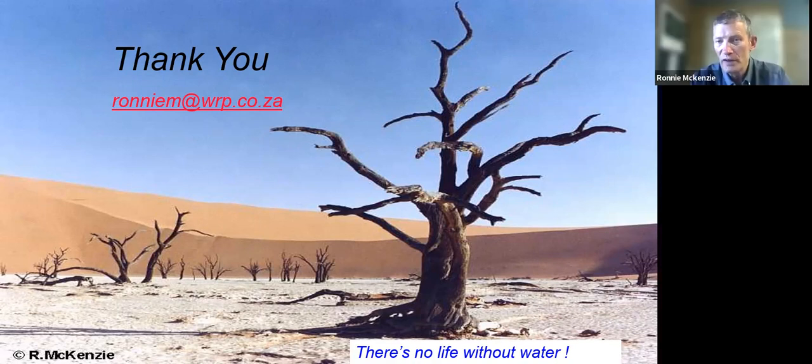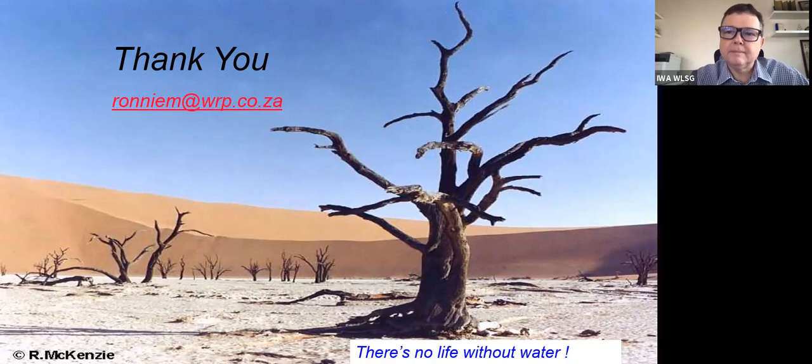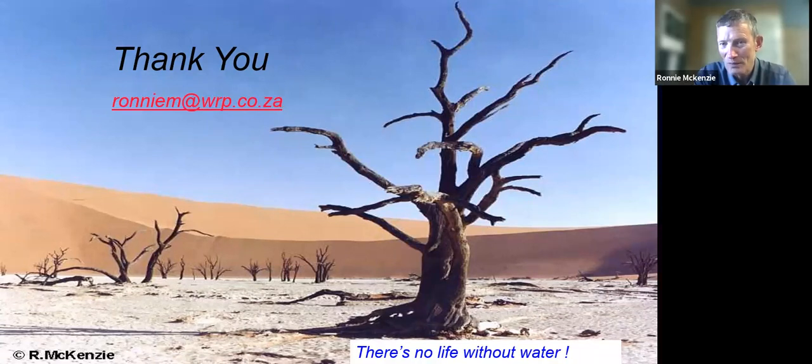Yeah, that's a good point. A lot of the houses in South Africa have a small PRV on the main connection going into the house, so that the pressure going into your house and the water tank doesn't exceed about 30 meters. So even whatever pressure reduction we do on the main system, if we don't drop it below 30 meters, it doesn't have a huge impact. But as I say, I think you picked up, is it Stephen? He clearly saw that we were hitting the demand. I didn't want to go into that, but anyway, that's a good point.